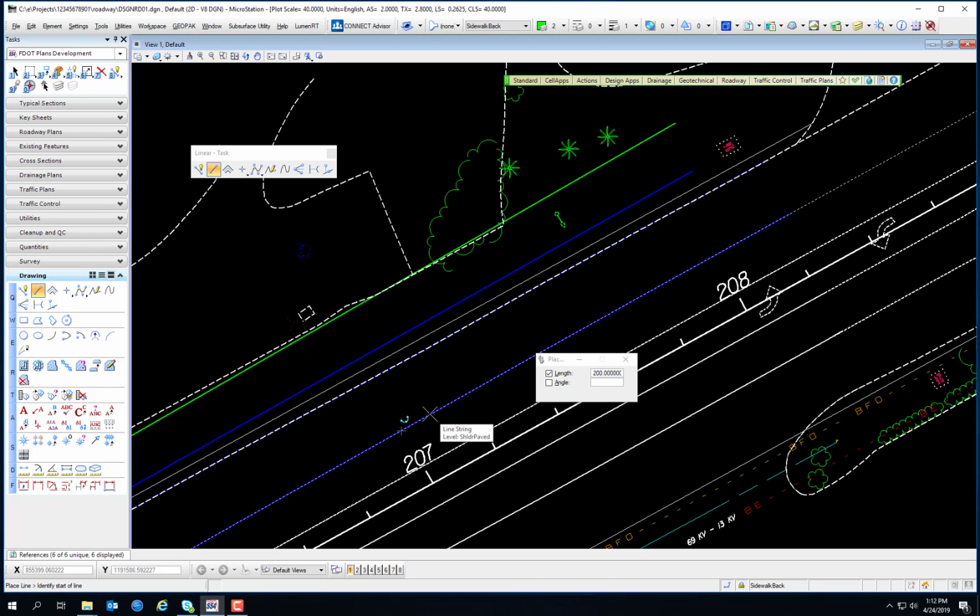but that demonstrates that you can set the length of the line that you're drawing by using the tool settings window. And this comes in a little bit later when we talk about drawing with precision. With AccuDraw, you will be entering numbers for length and angle and Cartesian points. So this gives you an idea that it's not just all about clicking a point here and clicking a point there. You do have control over the length of lines and the positioning of lines in more than just clicking on points on the screen. You can actually enter that data directly into the tool settings window.